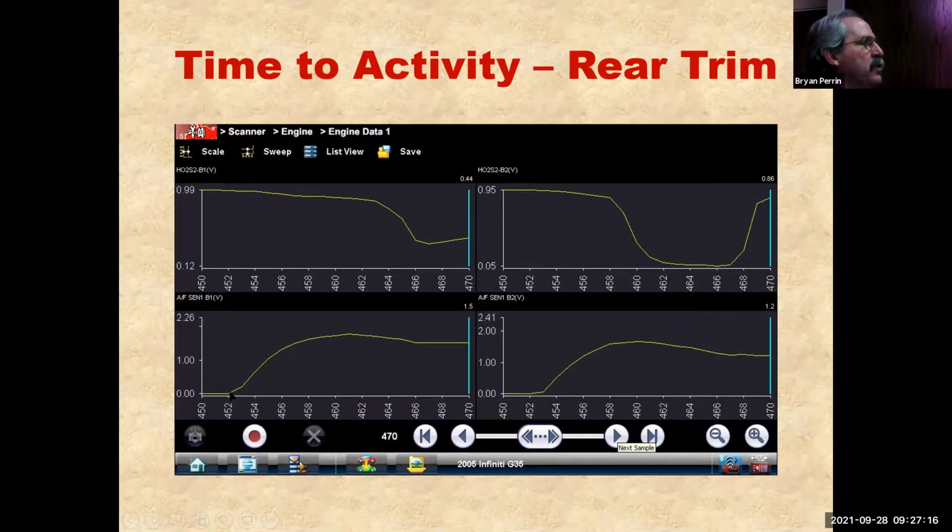My air fuel ratio sensor comes up. It's active, goes up to a volt, up to here. Here's where it's the highest. And as it's high here, we can see I'm dropping a little bit, because remember, higher voltage is lean. So it comes up to about here. We start dropping. As it drops, this starts dropping. This makes a correction and starts going back up right here. And this flat lines, and we end up at 1.5 volts.